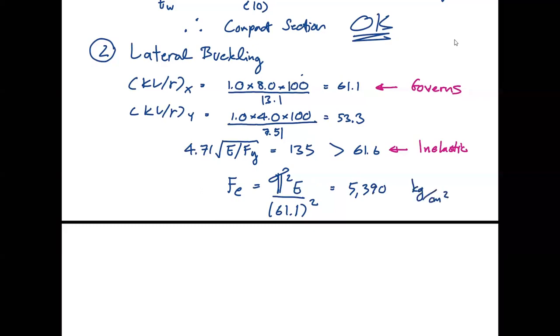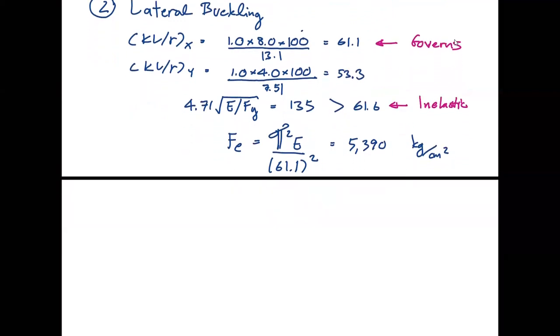Wow, this is bigger than Fy. Is it correct? Yes, it's correct because this is the critical elastic buckling stress. It's not the critical buckling stress itself.